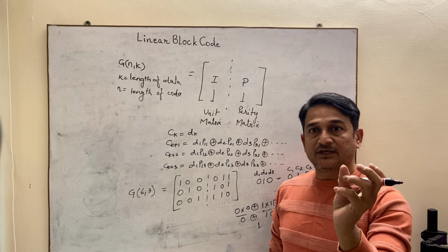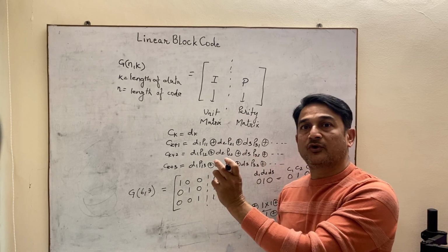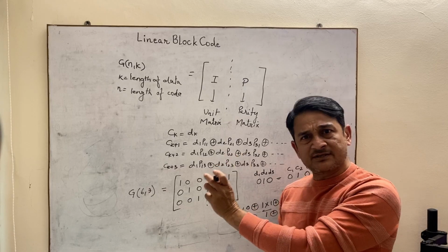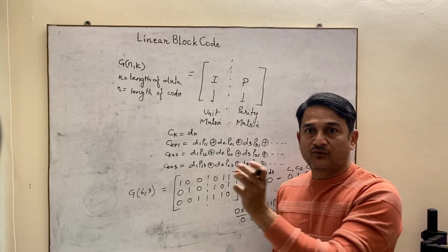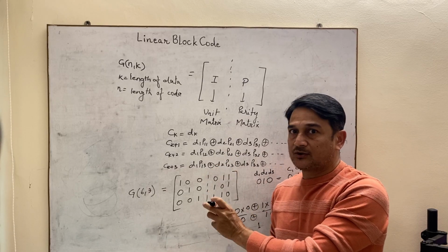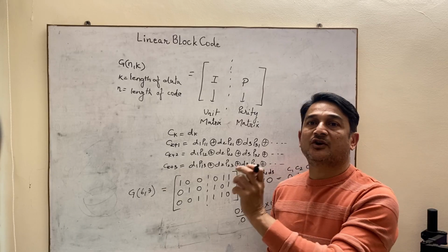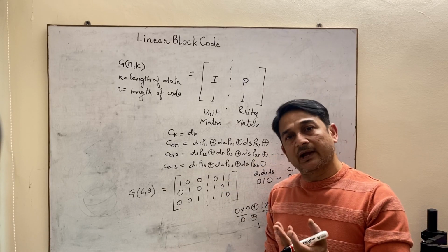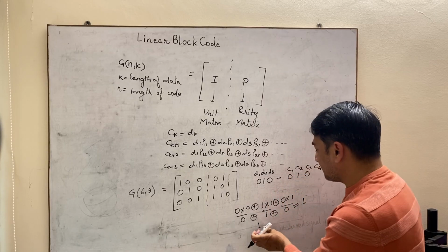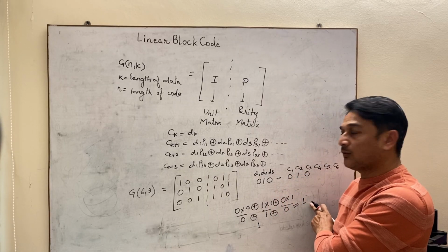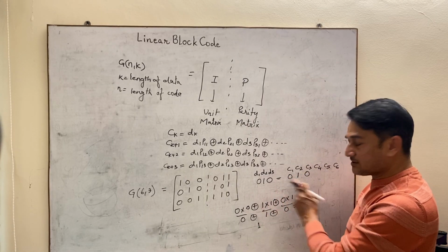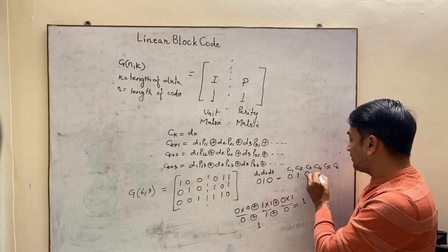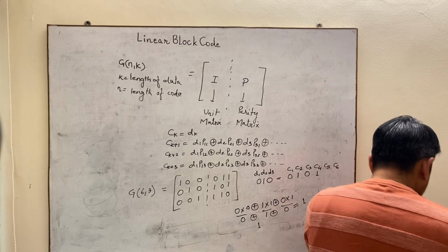You know the XORing of the binary values. If 0 XOR 0, then the output will be 0. 1 XOR 1 will also be 0. That means if the same bits are XORed, the output is 0, and if different bits are XORed, that is 1 and 0, the output would be 1. So from this calculation, your C4 bit will be 1.